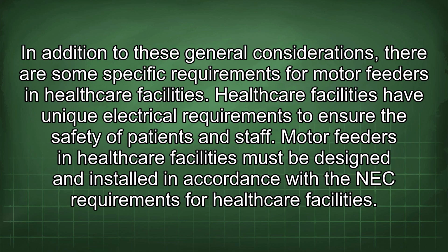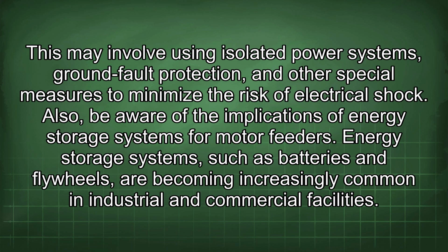In addition to these general considerations, there are some specific requirements for motor feeders in healthcare facilities. Healthcare facilities have unique electrical requirements to ensure the safety of patients and staff. Motor feeders in healthcare facilities must be designed and installed in accordance with the NEC requirements for healthcare facilities. This may involve using isolated power systems, ground fault protection, and other special measures to minimize the risk of electrical shock.